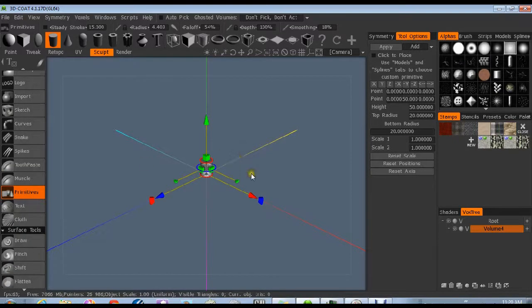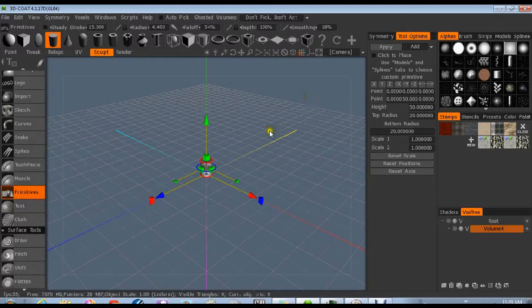So I come into this with the ability to add a cylinder to my project. And now the thing we want to do first anytime you bring a primitive in is set its orientation and its size. Let's turn on the grid so we can get an idea of how big this is, because the size of our primitive is also going to determine its resolution. This is the only time that I'm aware of at this point that the startup of an item actually chooses the resolution of that layer as well.